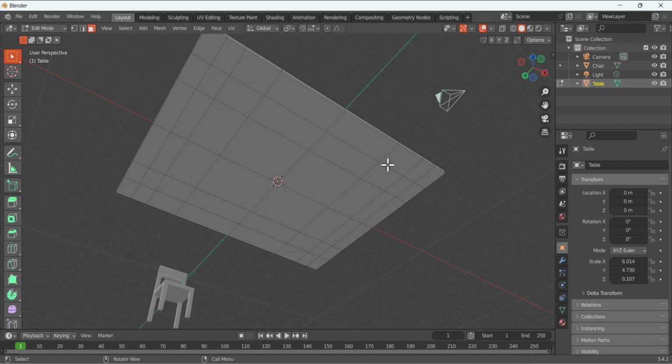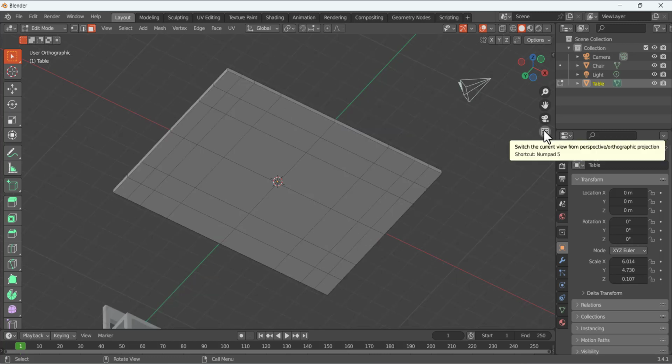And here we have a tool if you want to see the projection, perspective or orthographic, you can see that. So this orthographic is good. So now select these faces, press the shift, select this face, and these four faces of the corner.